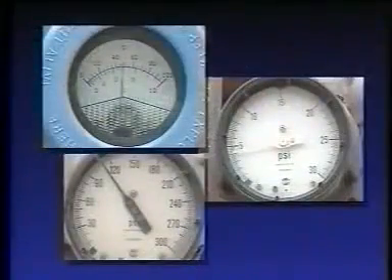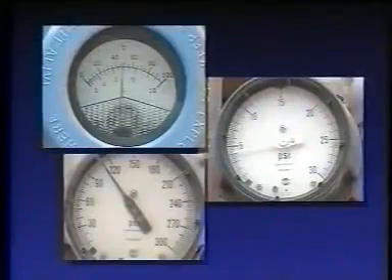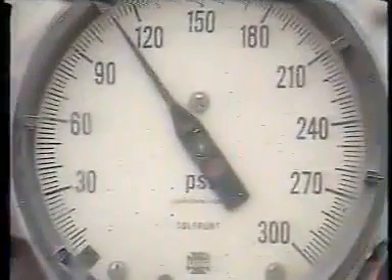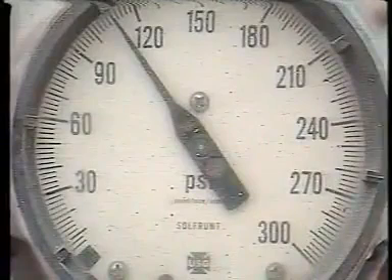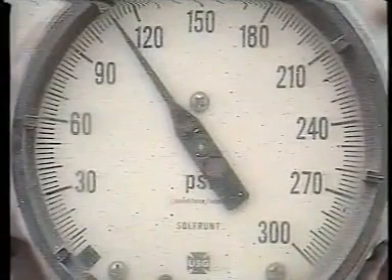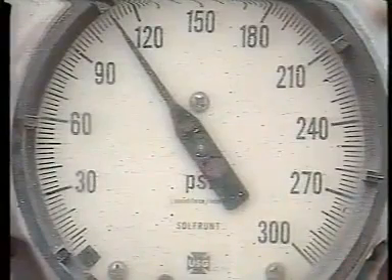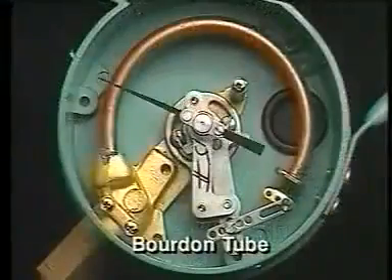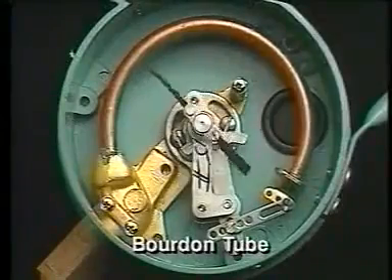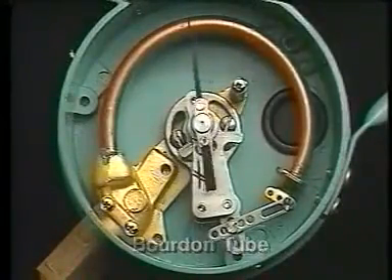Pressure in a vessel, inside piping, or at a pump is usually measured with a mechanical gauge. Most gauges show pressure by a hand that moves across a dial. Getting the hand to move accurately with the change of pressure is the job of the bourdon tube. The bourdon tube by itself consists of a piece of hollow, flexible metal.